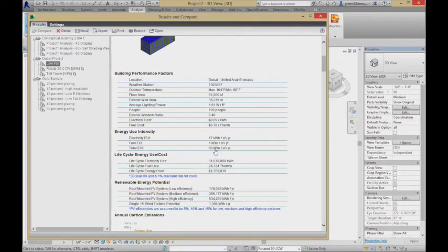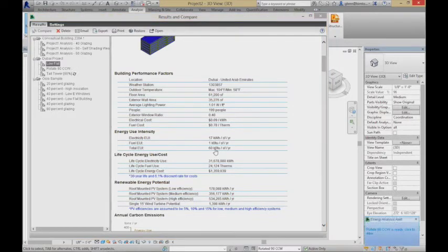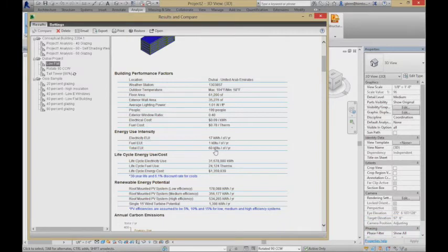Okay, so the energy use intensity of this building is about 60 kBtu. Okay, and that's not actually too bad. When you look at energy use intensities, you'll see all sorts of values and there's targets for what we'd like it to be. You can find buildings that have an energy use intensity of over 100. Trying to get anywhere lower than 40 or 35 is actually pretty hard. But that's one of those things that we don't really talk about very much. It'd be a really good, interesting measure just to say for all these buildings, what is the EUI? It's kind of a real quick measure of how healthy the building is from a sustainability standpoint.